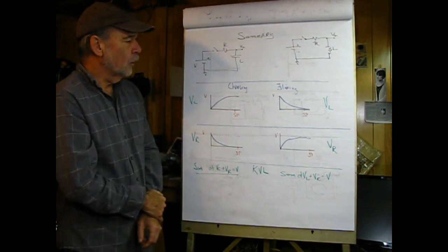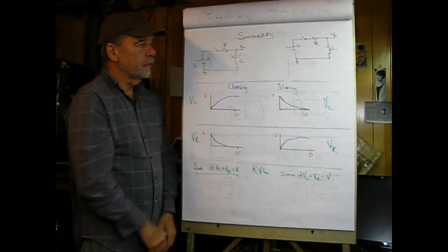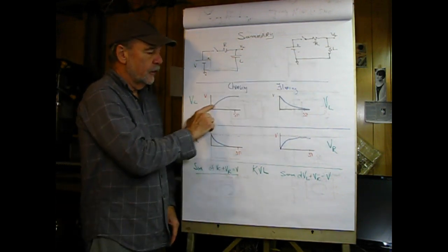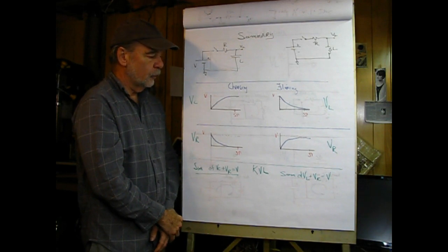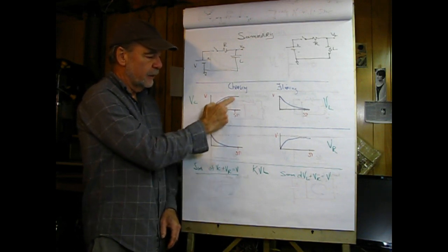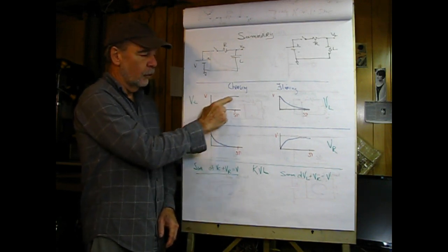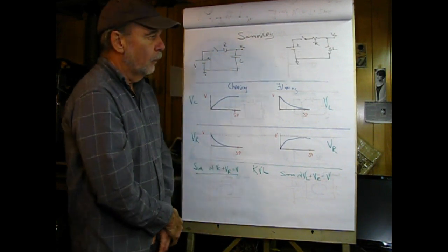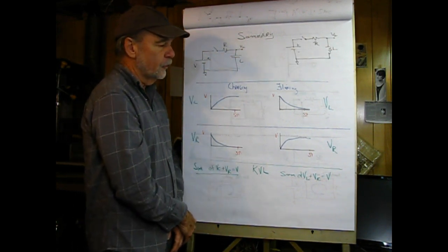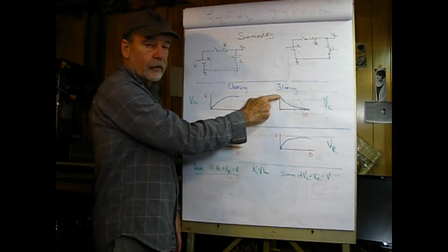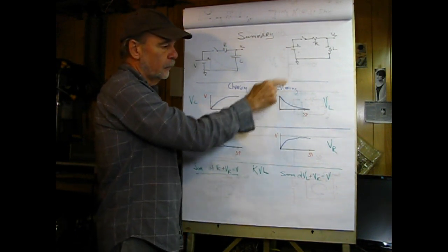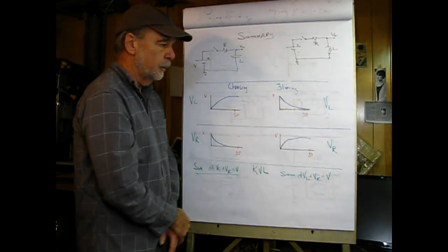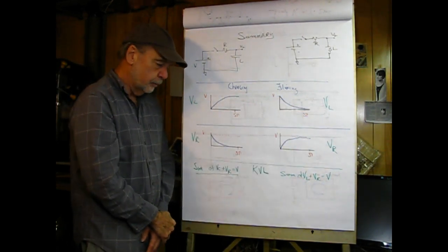So in summary here, we're going to start out with our RC circuit, and over here we have our RL circuit, and the charging of the capacitor here, as we saw before, would be at 5 time constants. We see that the capacitor voltage would approach the source voltage V, and when we're fluxing the inductor and the switch is closed, we see that the voltage across the inductor is maximum, V, and exponentially decays, and at 5 tau is considered to be 0 by the industry.